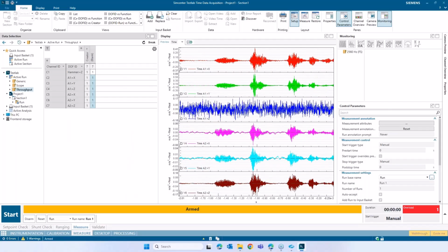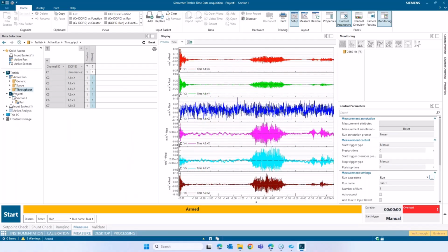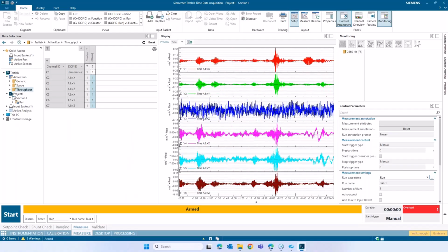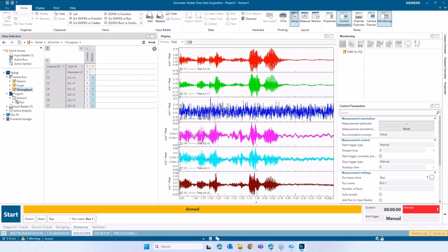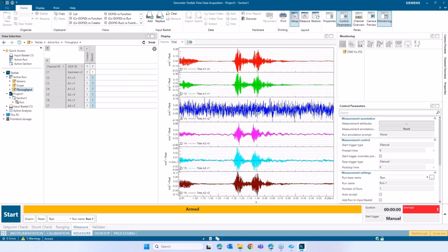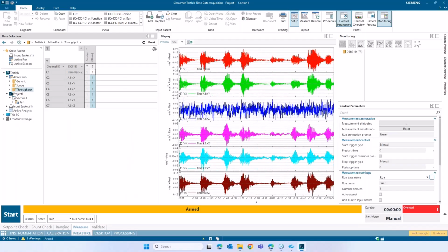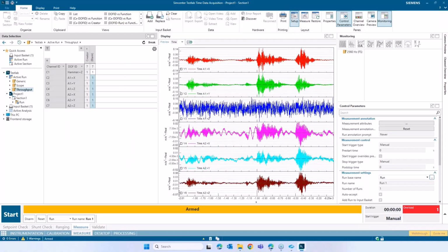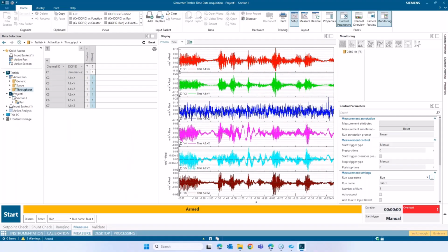So while taking the data itself, we can set it up such that we can do this check, and immediately after each acquisition, we will get that summary table of indicators telling us whether the channels look okay or not. Based on the numbers shown, 1.11 means the channel looks good, and 8.888 means there may be something wrong. You may want to check.